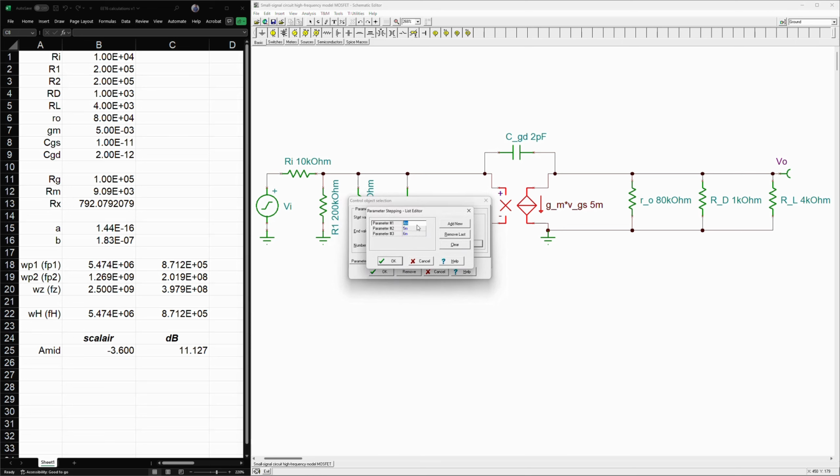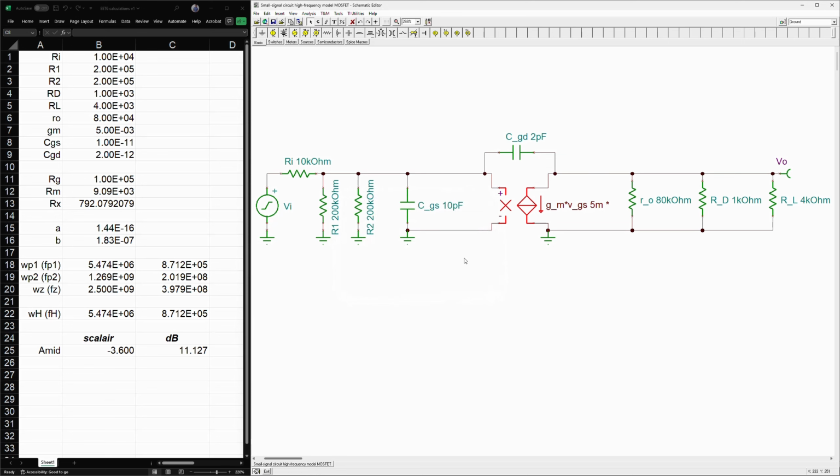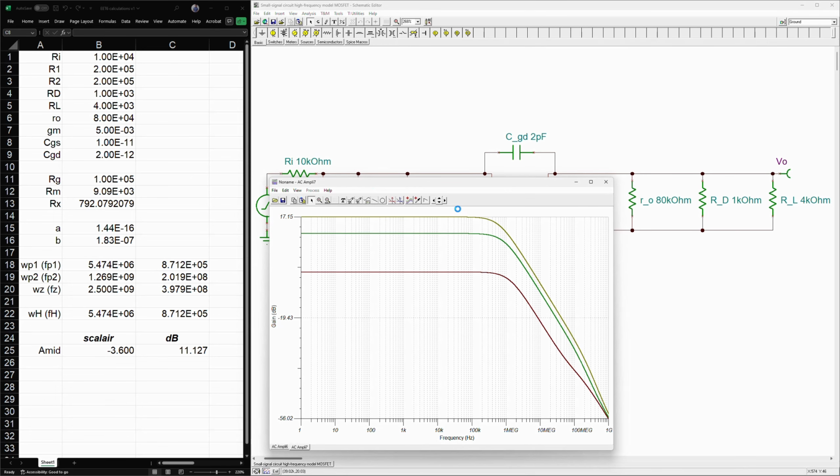I will now do here again a list. Let's say I will make it 1 millisiemens, and I will keep the second one as 5 milli as we had it, and I will now make it also 10 milli. So I expect for 1 milli a smaller gain, and the gain as we have it, and then here a much larger gain. Again you see an asterisk here, it means it's controlled. Now we will again do the Bode plot, same thing. And now we will run this, and let's see what the effect is now.